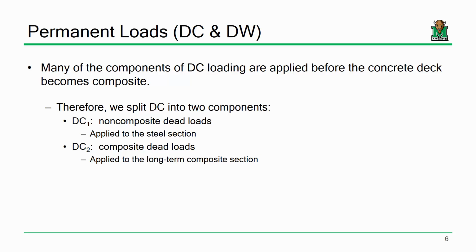Remember the difference between the short-term section and the long-term section was the deck got smaller, and we said that we needed a long-term section because that section represented the concrete's loss of capacity over time. These loads are always there. There's always a barrier on the bridge and what have you. So does everybody understand the difference?